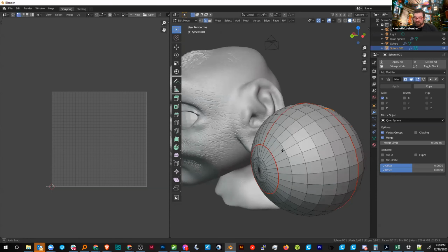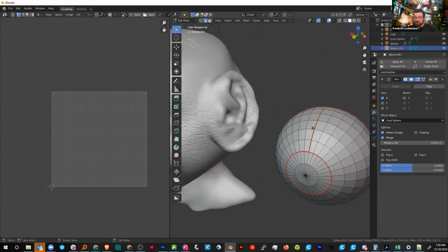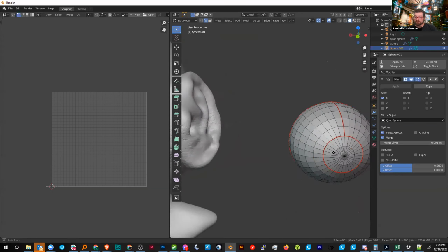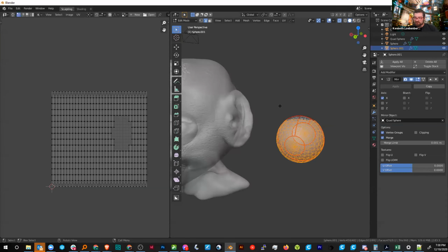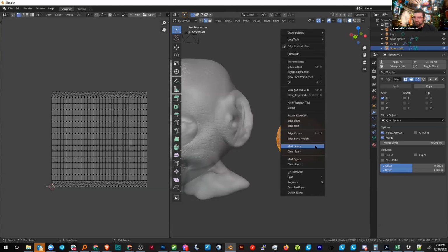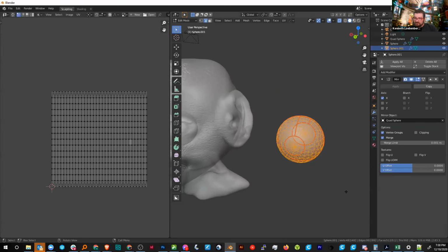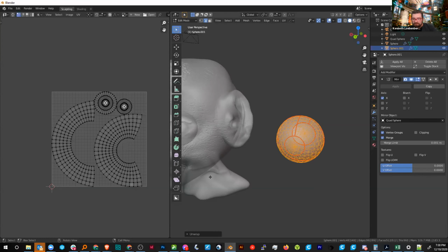what we basically did is we told it, hey, I want to cut apart this mesh so that it lays flat, and I want you to cut it apart on these seams that I've marked. So if I come in here, I can use my X-ray view, select it all, and hit U, and then I believe it is Smart Unwrap, maybe? No. Is it just unwrap? Sorry, it's been a while since I did this. Unwrap. There we go. Okay, so now you can see we got this unwrapped here.